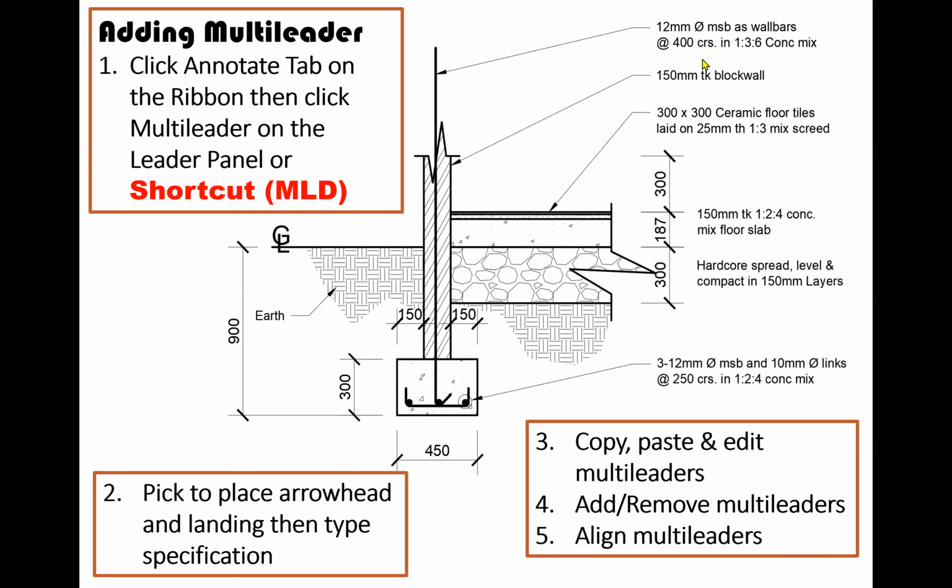Well, you basically give some form of quantity when you say that it is every 400. It didn't tell you how many steel it will take because, of course, the length of the wall will determine that. But you still have some amount of quantity because you're telling that it's happening at every 400. In other words, it's happening at every other block pocket. So we have the things called out there.